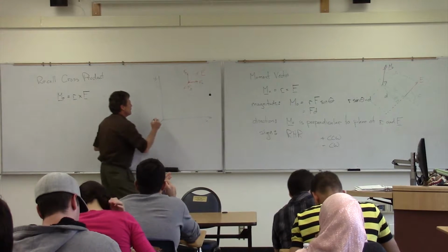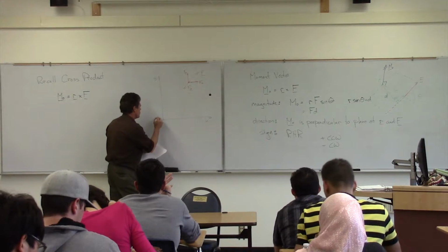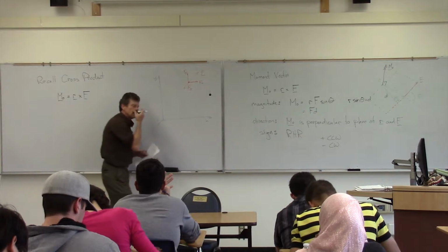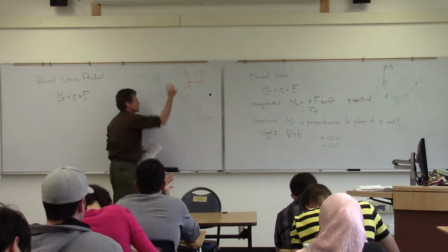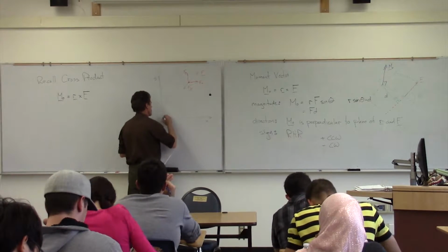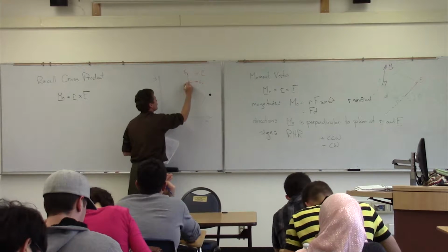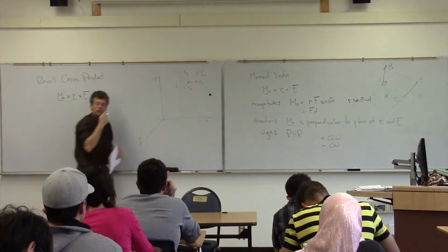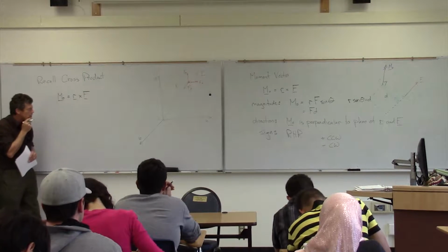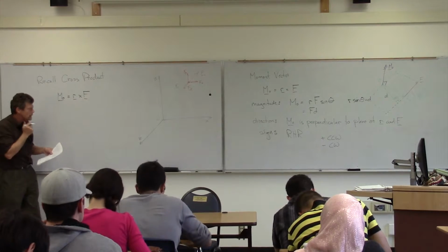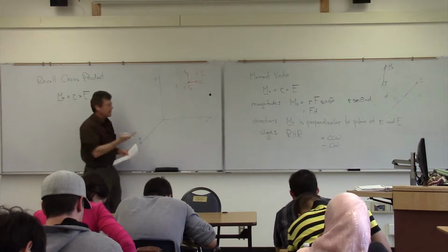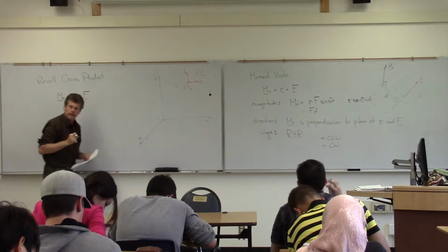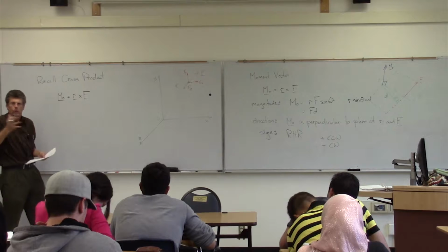Now, if I want a moment here, and we'll call this point O, to draw a moment there, I'm going to need to draw a position vector to somewhere on the line of action. In this case, we'll just draw it to that point where the end point is, where it's actually being applied. Now, again, I can break that r component, that position vector, into x, y, and z components.